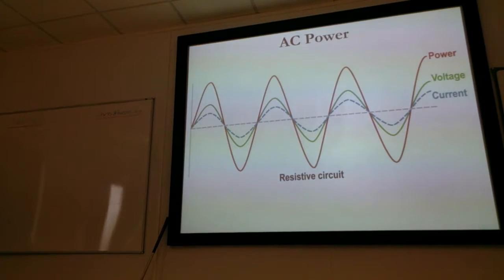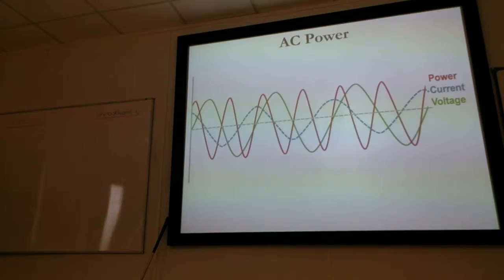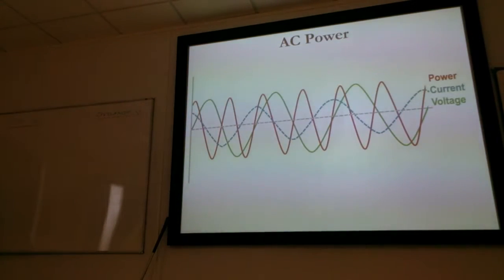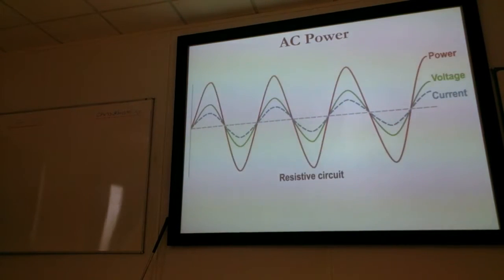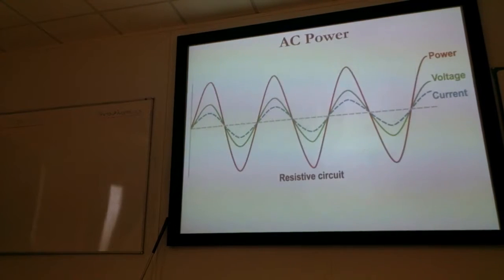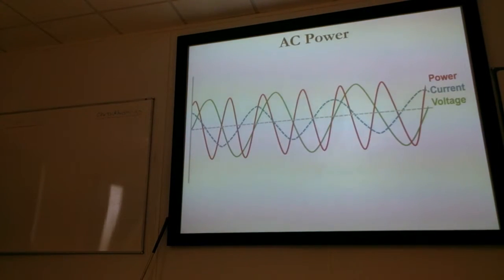If we put that out of phase, look what happens to our power peaks. Because it's a confused situation where the current and the voltage are out of phase, the sum of the two means we've got much less useful power. And if I just flick between the two, you can see how profound that difference can be. Same voltage, same current, but just putting them out of phase gives us a massive reduction in power. Now we see why we need to care about capacitance and inductance.